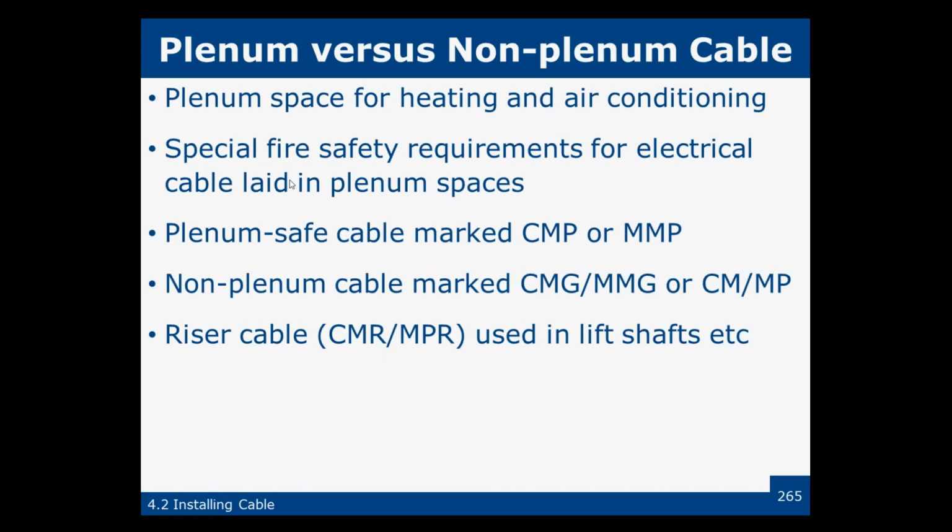There are special fire safety requirements for electrical cable in plenum spaces, and plenum cable will be marked. They say it'll be marked as CMP or MMP. What I've seen on most of it just says plenum on it. General purpose cables are marked with CMG/MMG or CM/MP. So we have the markings.